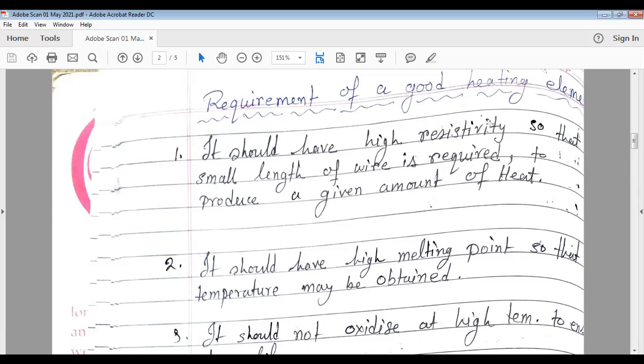Here is a square-type furnace where the whole inner surface is covered with nichrome wire, and it produces a lot of heat. The gold or metal is put into a crucible under this furnace, and after a specific time, using some flux, we can melt this type of metal and use it, but it is for small amounts, not large amounts.